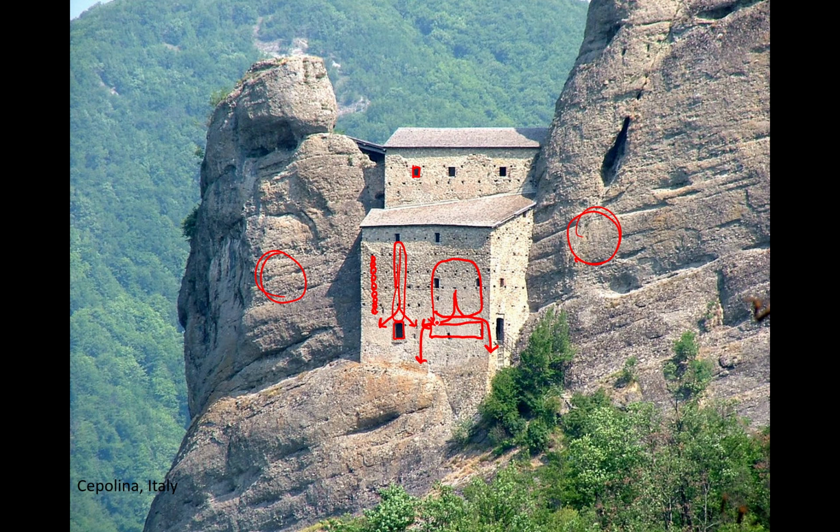We'd need something like a really strong concrete beam or a steel beam to exist here as a header above the window and take the weight of all of these stones and distribute them down and across and into the ground. So fundamentally, when you see modern buildings, we use modern materials to be able to distribute those loads to let us have large glass windows or wide horizontal windows versus older buildings that will have more narrow and taller vertical windows and doors.